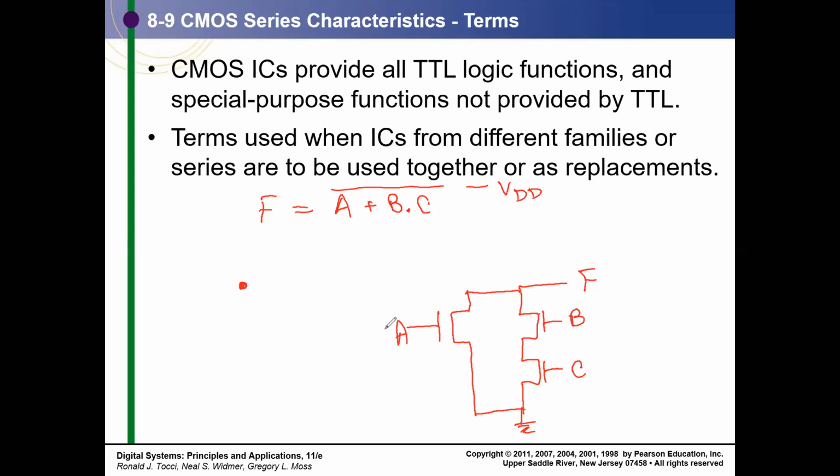So you draw the network for N. Every transistor becomes a branch and every node, this is one node, second node, and third node. Every source and drain wherever you have are the nodes, and you can draw the graph. So this is A, and on this side you have 2 branches like this. This is B and this is for transistor C. So this is the graph which corresponds to the N network.